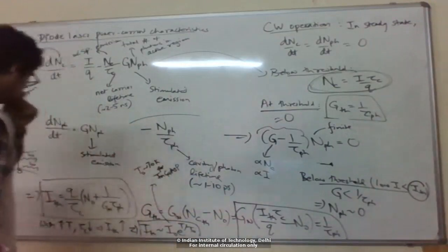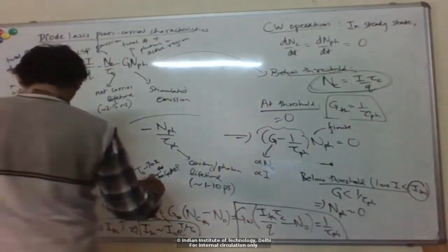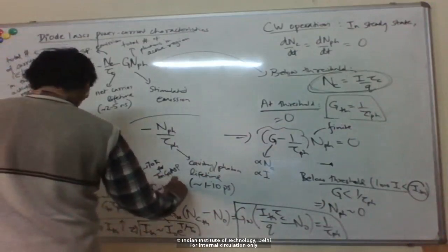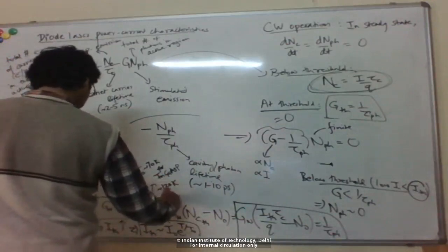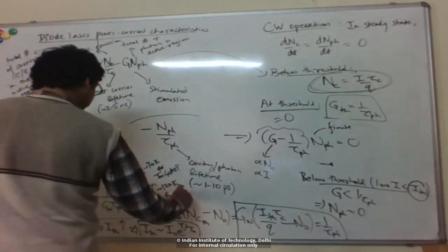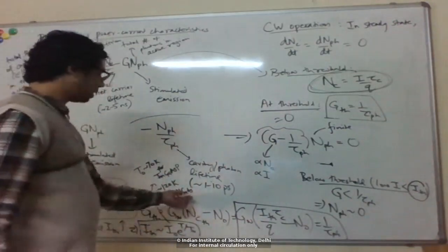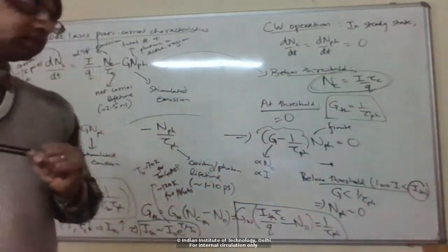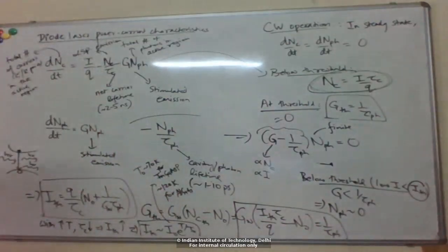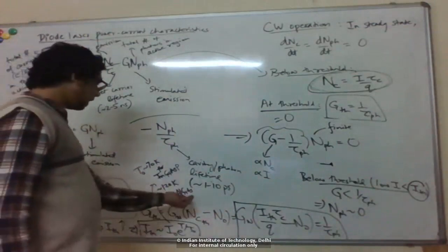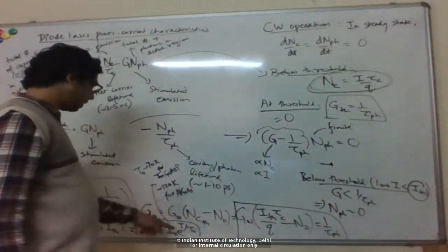for the telecom devices. If you go to slightly shorter wavelengths, this goes up to about 120 Kelvin for AlGaAs devices. So AlGaAs devices, remember, they operate around 800 to 900 nanometers. So in terms of temperature performance, AlGaAs are more stable because the T0 is higher.